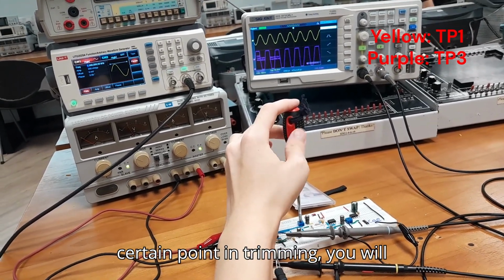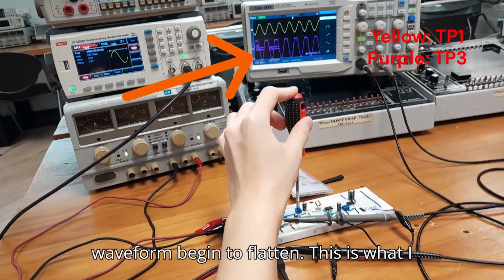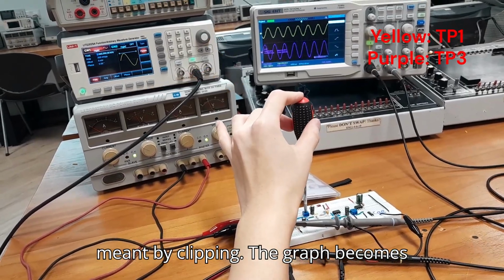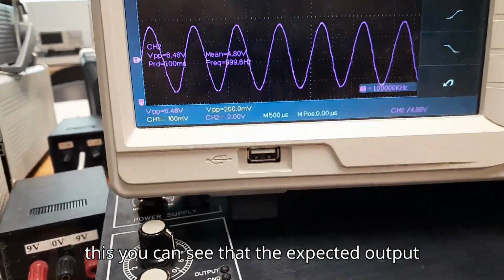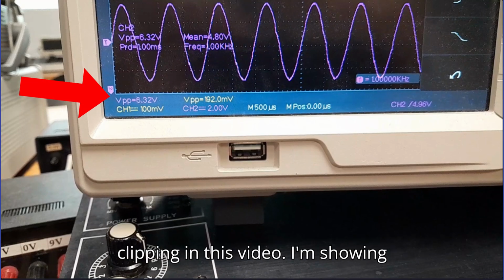After a certain point in trimming, you will notice that the peak and trough of the waveform begin to flatten. This is what I meant by clipping. The graph becomes saturated after a certain voltage gain, which results in it being cut off. From this, you can see that the expected output waveform should be around 6 volts without clipping.